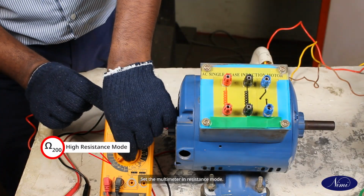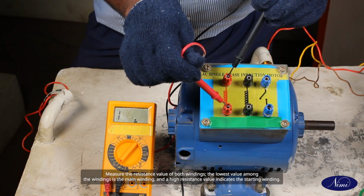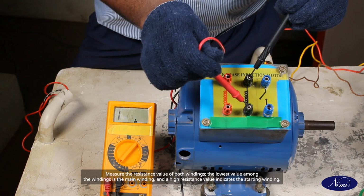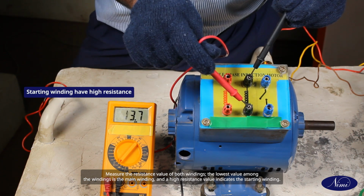Set the multimeter in resistance mode. Measure the resistance value of both windings. The lowest value among the windings is the main winding, and a high resistance value indicates the starting winding.